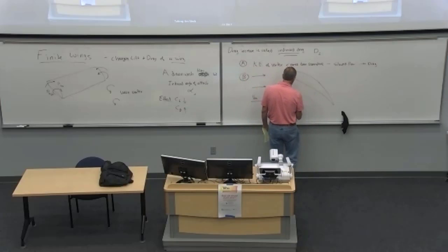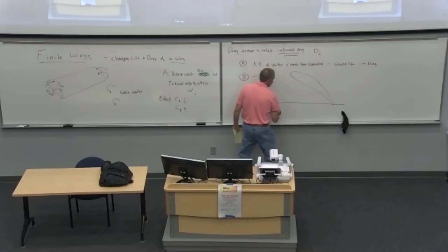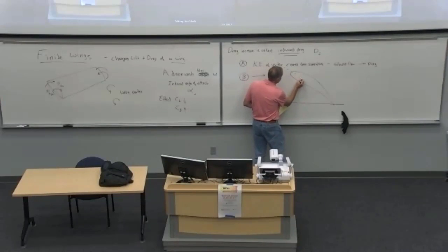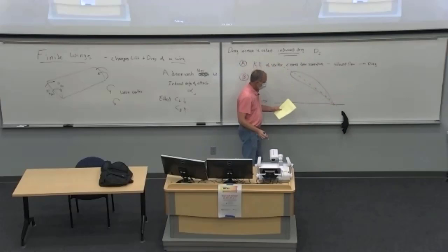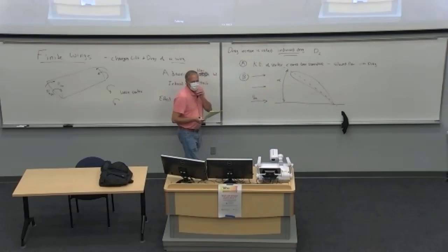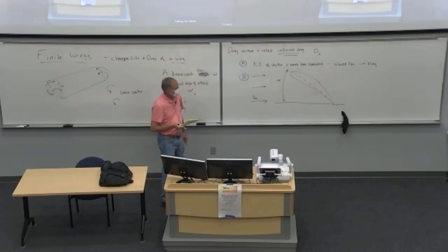And I've really exaggerated the angle of attack here for a reason, so that we can see the angle. You draw the chord line through the wing, which would be an average chord of all the airfoils. Then that's the angle of attack. And if this were an airfoil, we'd look up that airfoil at that angle of attack, and we could get the lift.